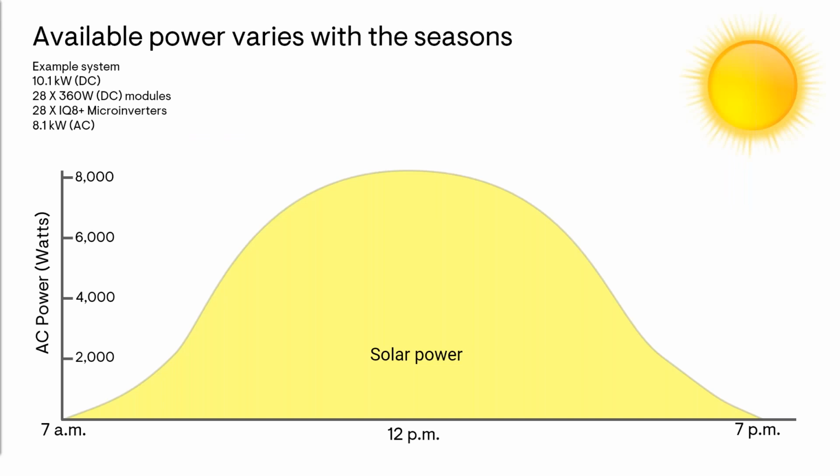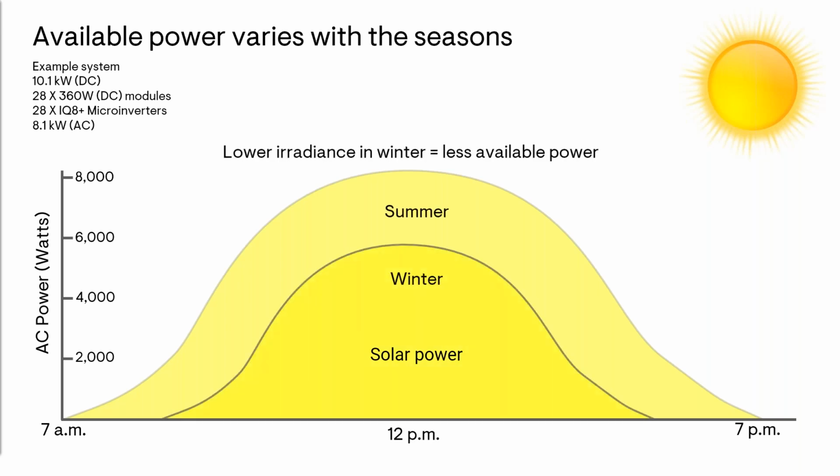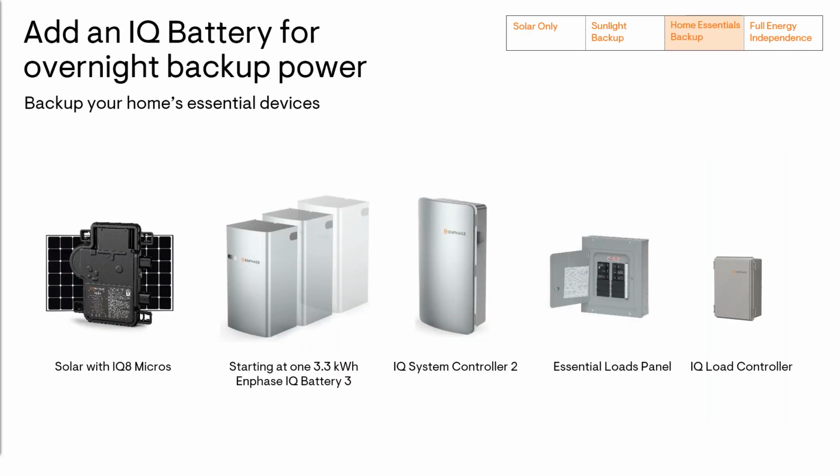It's a common misconception that inverters are delivering their full rated power whenever the sun shines, but this isn't the case. The power output of a solar inverter is relative to irradiance, again, or the intensity of sunshine. Irradiance is naturally lower in the winter than the summer. A solar inverter system with a rated power of 8 kilowatts may only reach around 5 to 6 kilowatts in the winter. Winter days are also shorter than summer, so the window during which the solar system could potentially power the home is going to be smaller.